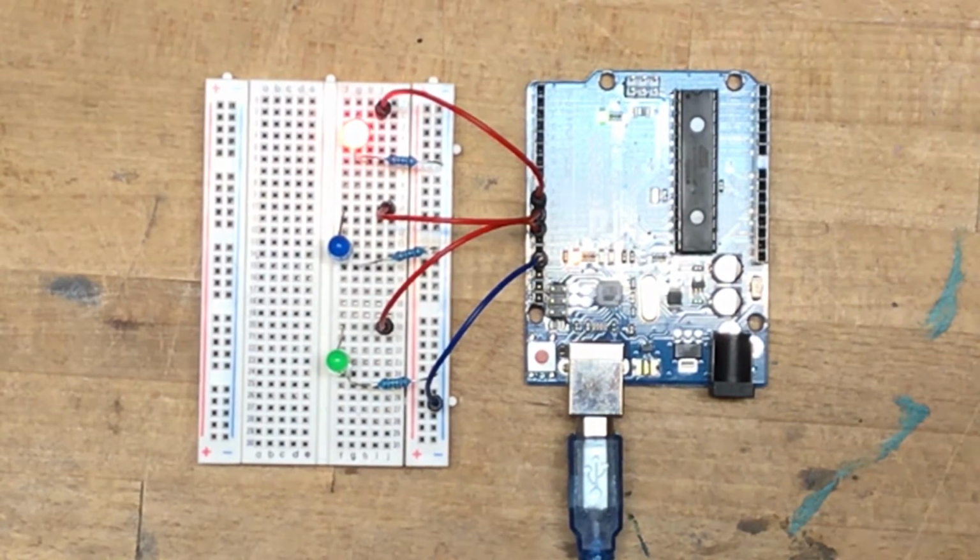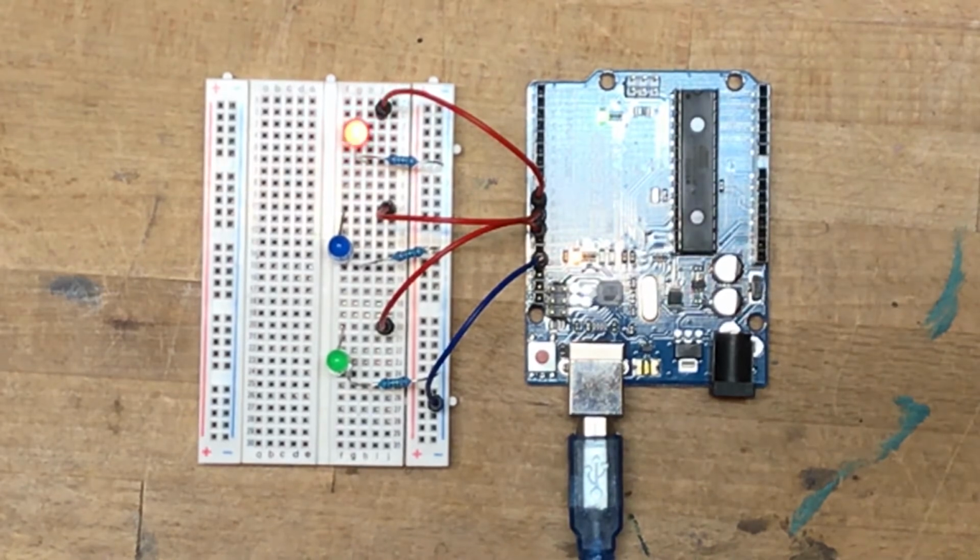So you can see this LED isn't just on or off like they've been all through last week. This is actually fading on and off, sort of emulating something analog. What I mean by that is thus far we've been working with a digital signal, either on or off, 1 or 0, high or low. In this case, 5 volts being high, 0 volts being low. Now we're going to be playing around with approximating an analog signal, something that can exist in between those two values. And we're going to be doing that with this same series of LEDs. So just make sure they're in pins 9, 10, and 11, the ones with the little tilde, the squiggly mark next to them, and we'll get started with the code.